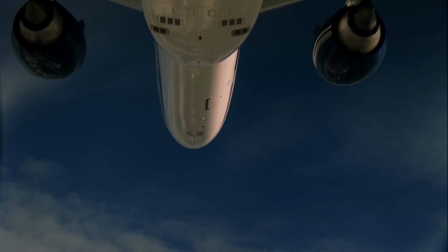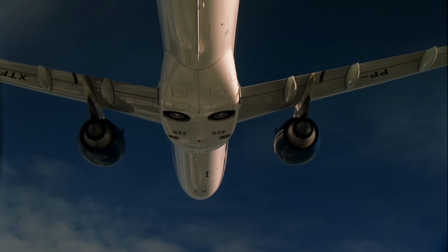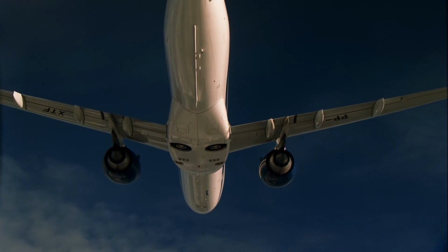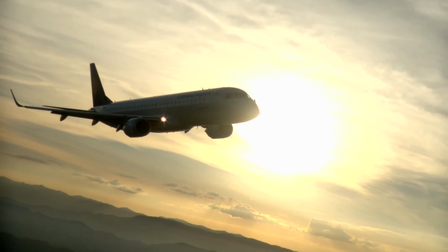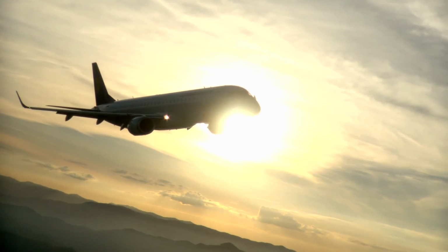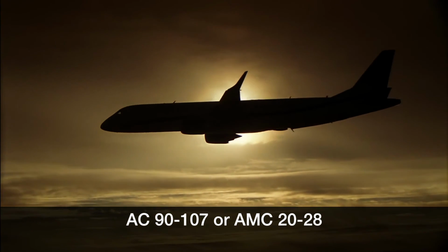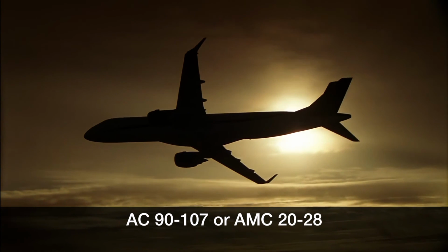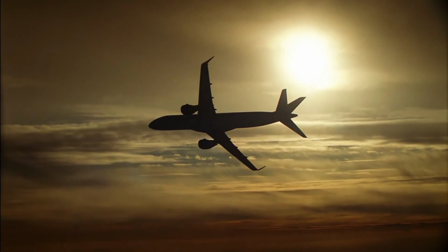RNAV approaches with LPV minimums, together with SBAS systems, provide an efficient alternative to traditional ILS approaches. This video has been an overview of RNAV approaches to LPV minimums. Please be sure to refer to AC 90-107 or AMC 20-28 and your aircraft pilot manual for more detailed information.